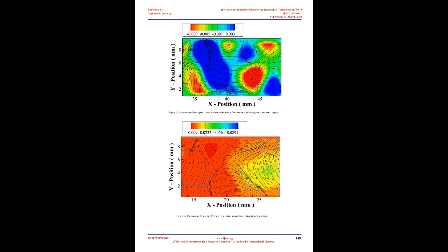Results. In Figures 8, 9, and 10, at 0.0084 m/s for the upstream section, the obstructed water flow behavior was shown by the circular scale pier model, using 10, 20 and 30 mm thicknesses. Vortex was appreciated at different positions due to the pier's thickness, going further back in the water downflow and upper. Hence, for downstream the turbulence was bigger, from slender pier to thicker pier, until hitting against it.